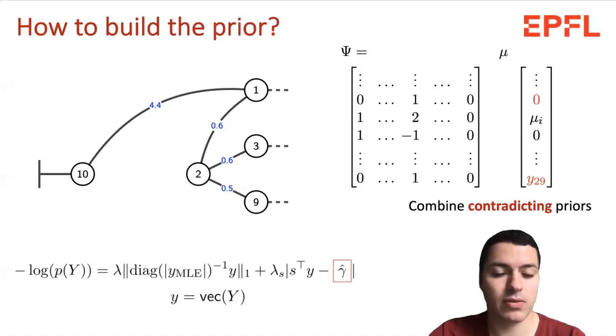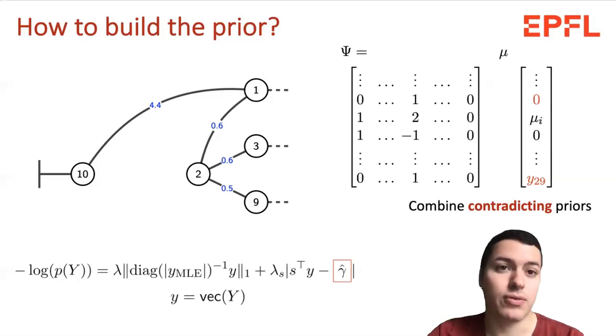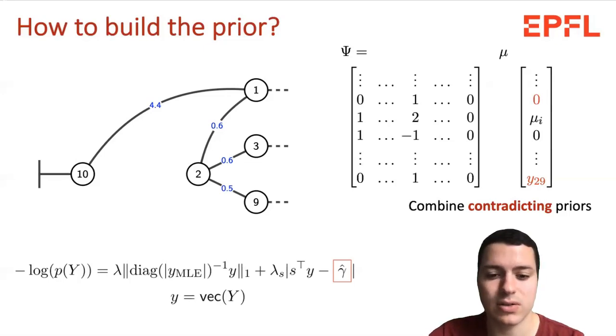This is one type of physics-based learning where you only use the sign of the parameters S here, which comes from the fact that the conductance is always positive and the susceptance is always negative if you don't have series capacitors. And essentially what it does is the first term is an adaptive lasso prior, which is asymptotically unbiased, but with finite sample size, it creates a bias to 0.